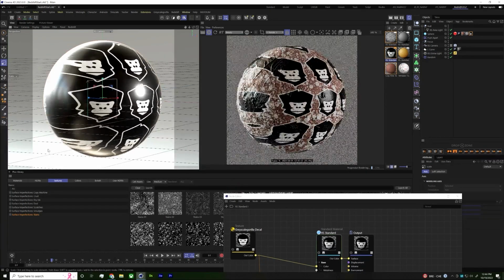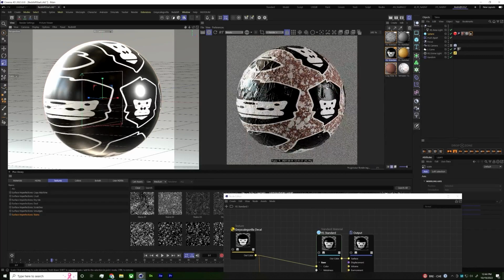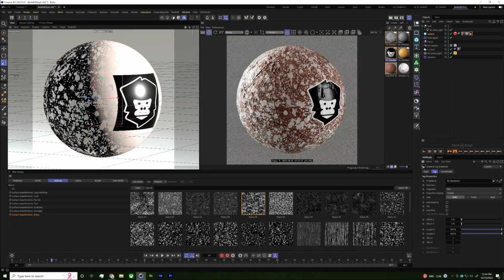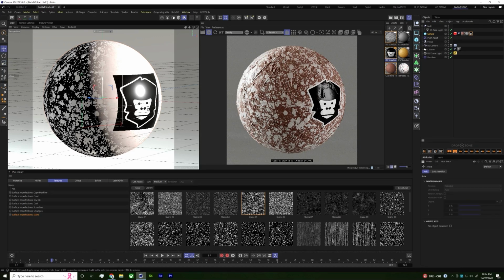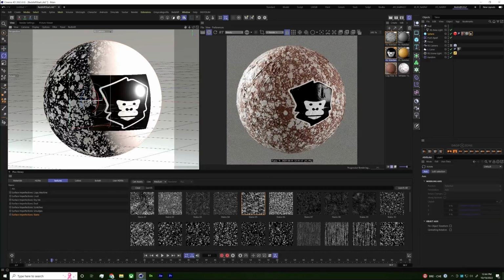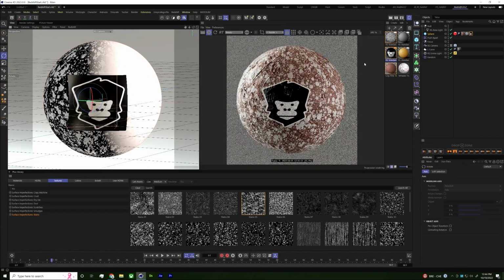I'm just going to use scale and click on my material tool right here, the material adjust tool. Scale this sticker down. And instead of multiple copies, I want to go into this material and turn off tile. So now we just got one sticker. Let's rotate this around just a little bit as well. Let's move it across, and let's use our rotate so that it's more straight on.